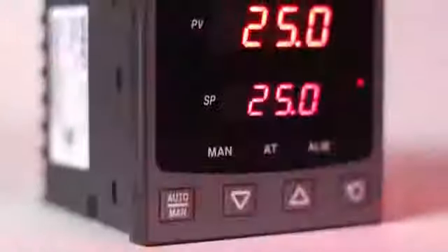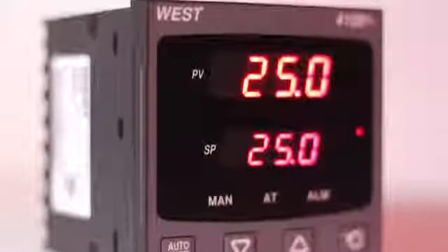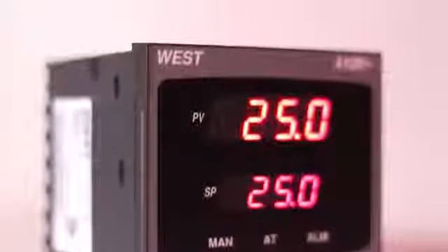The uses for these alarms are almost endless. It really depends what is important for you in your process. Deviation and band alarms are used to draw your attention if the controller is not able to keep the process within the boundaries that you have set. Another example is the use of two process high alarms, one to shut the process down when an excessively high temperature is reached, and the other to act as a pre-warn below that point. The pre-warn allows the user to take some action to prevent the final high alarm from shutting the process down.